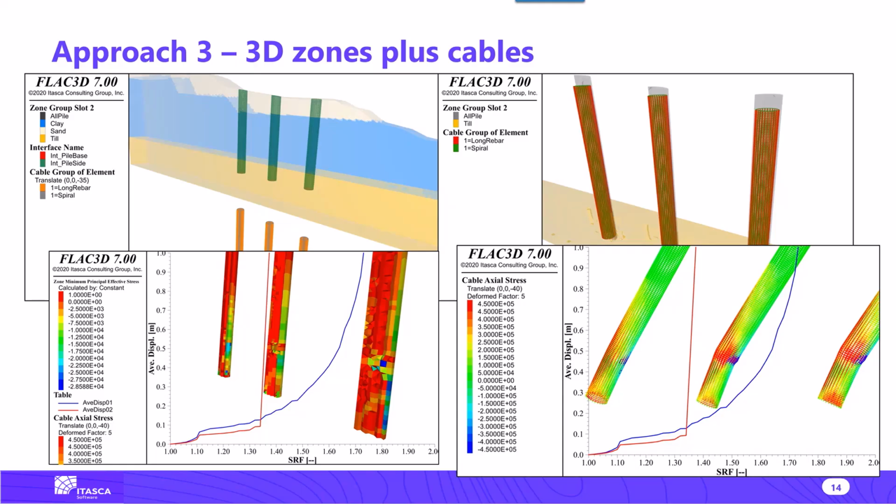So this provides us sort of the three approaches: from the simpler one, in which we're just updating the bending moment capacity as a function of the axial force; the intermediate one, in which we have two piles, one nonlinear pile for the concrete, and the other one a nonlinear element for the cage; and then the full explicit geometry for situations like in this one.